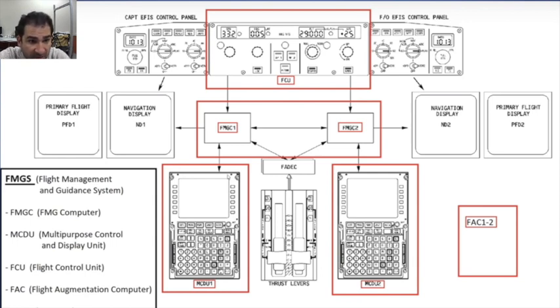And then it's also connected with the flight control unit. The flight control unit is the element you have in front of you when piloting, in which you can select heading, speeds, altitude as reference values, and this is engaged. This goes in the computer and is somehow connected with the display units, the navigation display and the primary flight display. We've seen that when learning how to fly on a conventional basis, and it's also connected with the MCDU, right? So this is the first thing I wanted to show.